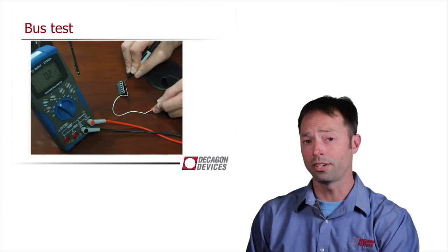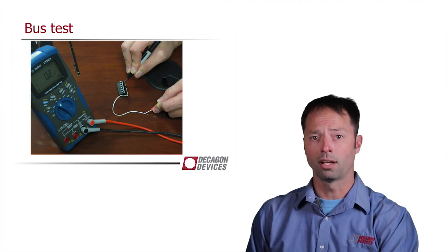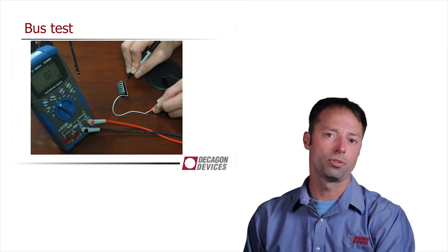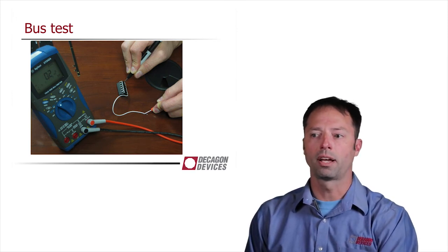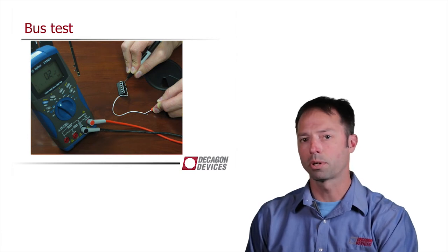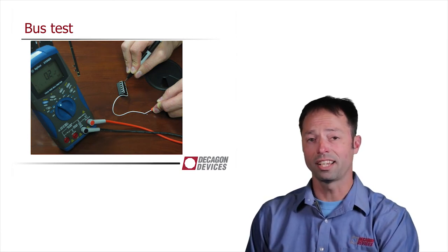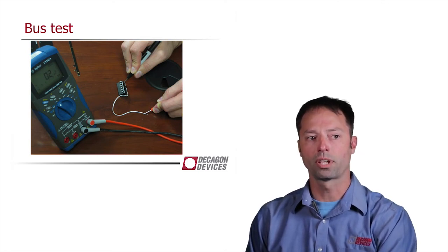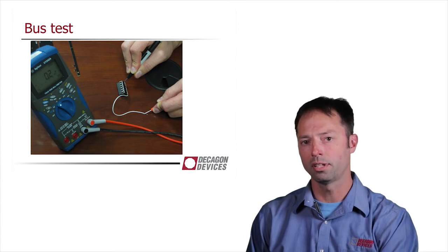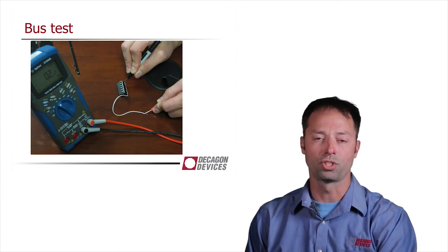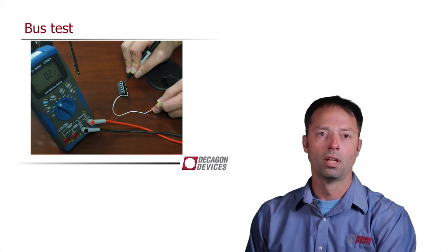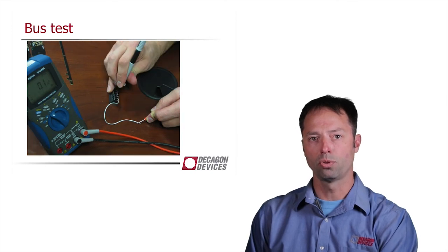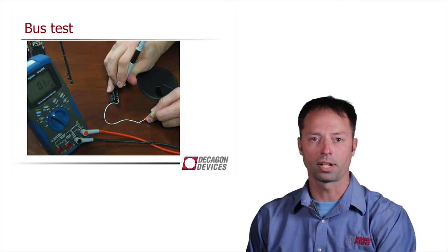It's a good idea to do a continuity check if you have a homemade bus. The previous case that I showed you in LoggerNet, that was the first bus I ever made personally, and I was not, and still am not, an expert at soldering. So there were several spaces that only had intermittent connectivity, and that turned out to just be a giant problem for my network in general. So most multimeters have what's called a continuity check, and you can just move down and make sure all of your ports have a good connection between each one.